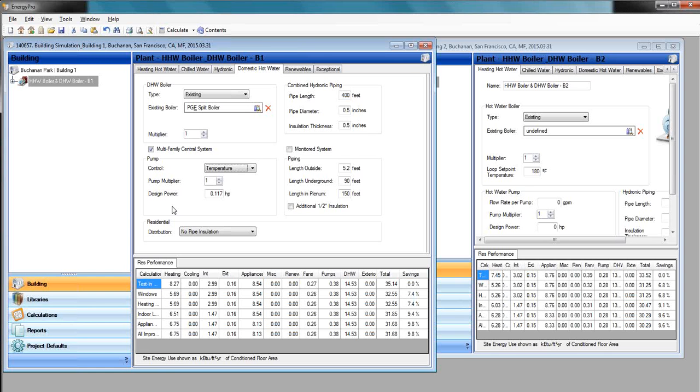The other thing that you might see out there is that sometimes pump energy is expressed in kilowatts. So you want to divide the kilowatts by 0.746 to convert that into brake horsepower. 746 watts is a horsepower, so that's why you have that.